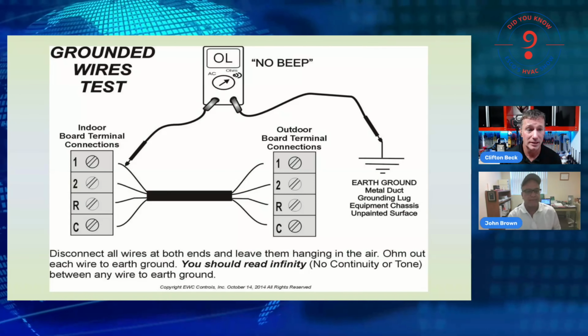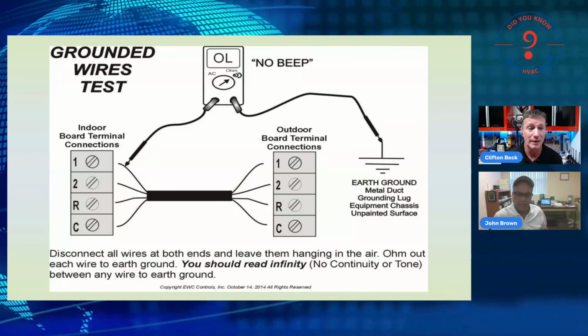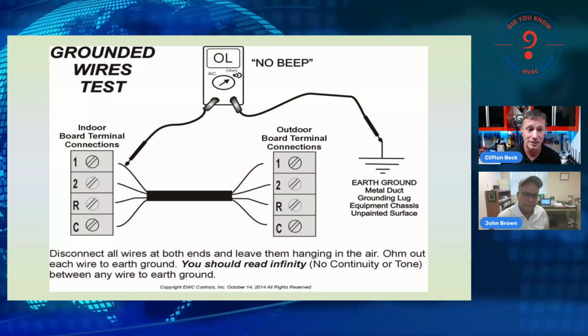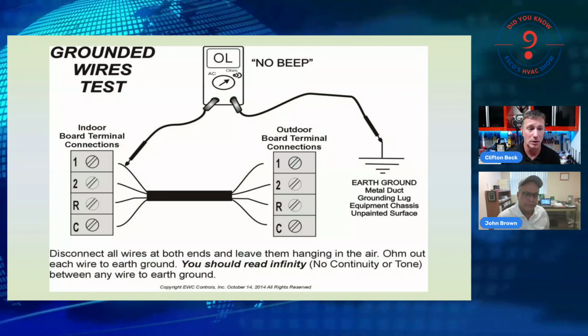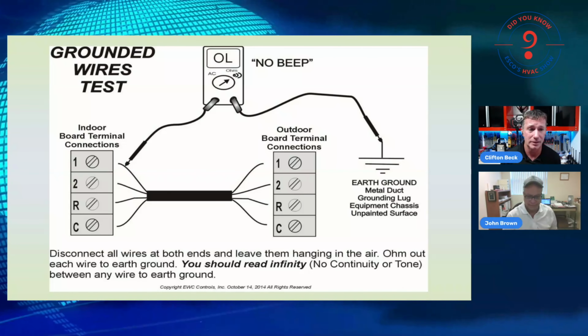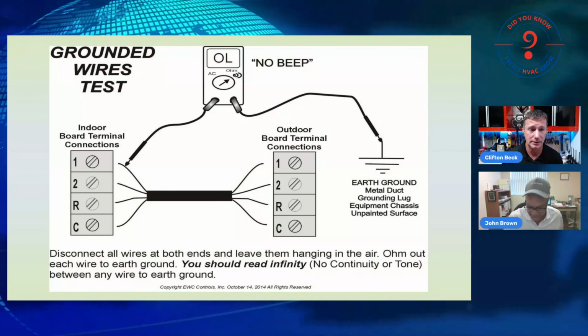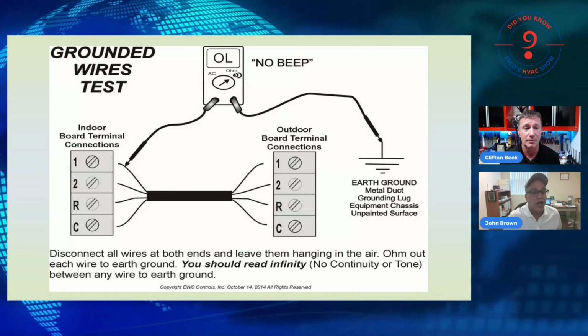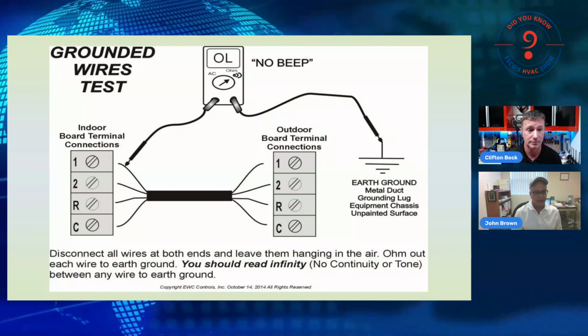Yep. Here in the Midwest, when we have a basement with a sump pump, a lot of our installations now we're using poly and PEX water lines and gas lines. You've got a sump pump, you grab your piece of copper wire, you strand it, and you shove it down into the water, and now you have a good, clean place to measure ground. So plenty of places we can find good ground. Good point. Thank you.